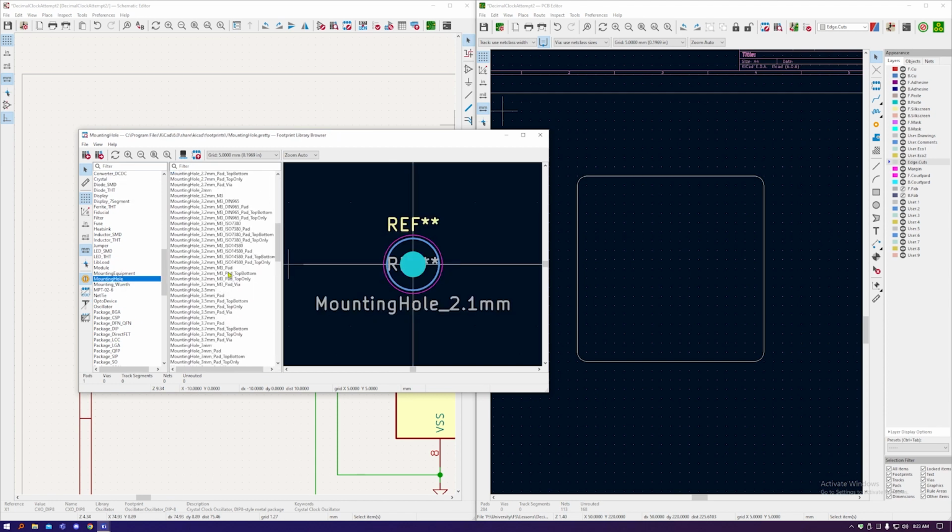So if you've ever used a motherboard, they're M3 standoffs, they'll use holes this size, and the best one is the bottom one, pad via. So that's because it's got vias, which are little connections between the top and the bottom of the PCB that go through it. They hold the pad on the top and the bottom together, and it's basically just the strongest of all the different options.